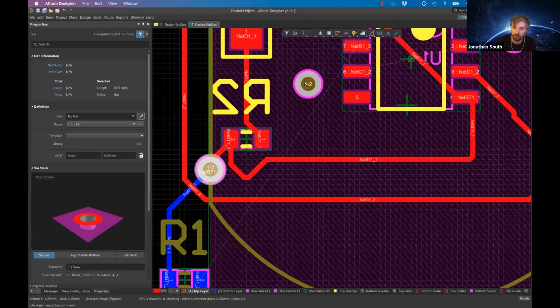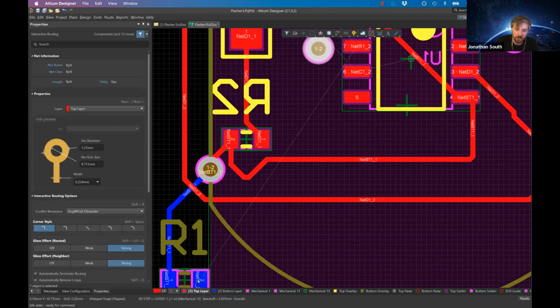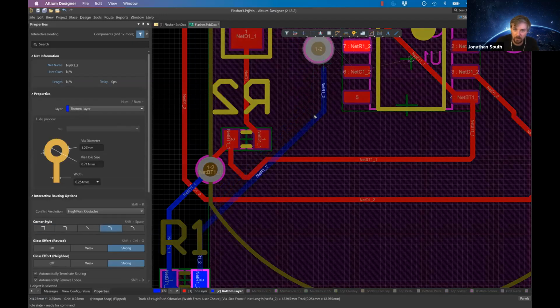If you're using a through hole, basically all the different legs of that through hole component are basically vias because they'll connect from the top to the bottom. So there's some advantages and disadvantages that we're seeing here. So that one needs to go to there. Let me place him like that. You might need to choose a smaller via size if that is helpful for you.